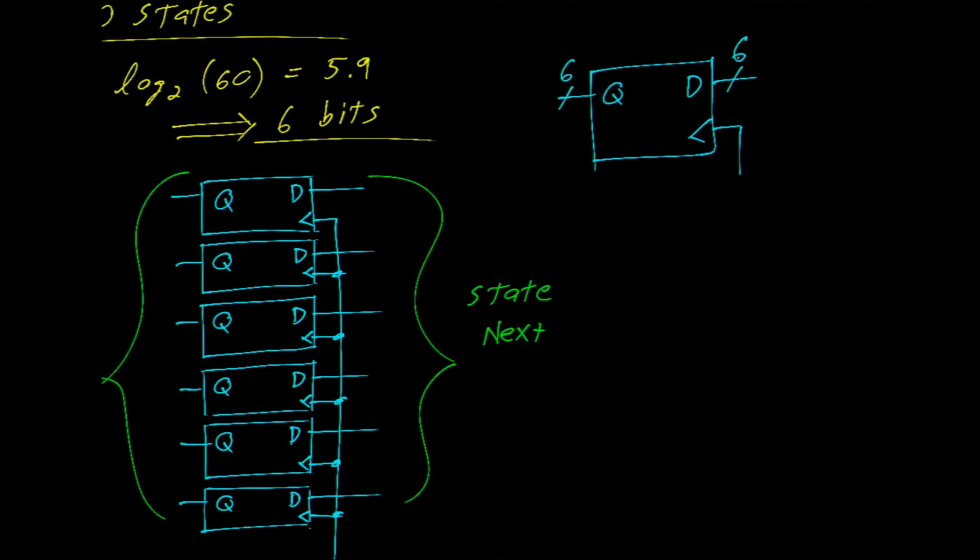All right, so that is a 6-bit register. 6 flip-flops all in a row working together on a common clock. So we could say that these two are equivalent, with this one being much preferred. Actually, this is a concept that's going to become more and more important to us as we move on, because we're going to move into hierarchical designs.